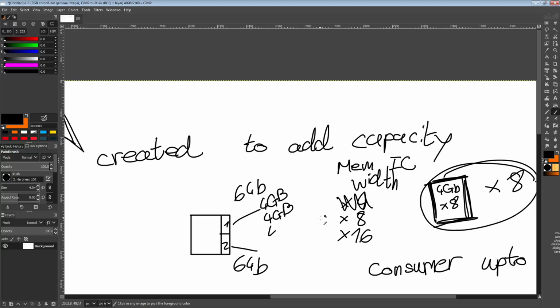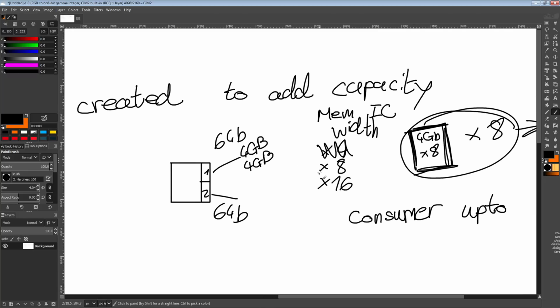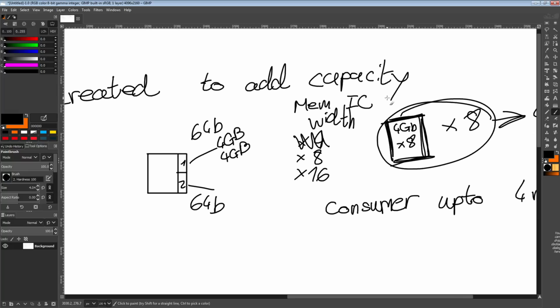Because then your motherboard needs to connect way more DIMM slots to the CPU, and you also take up space on the CPU die itself for the memory channels. So memory channels are very expensive. So memory ranks were created where it's just like, look, you can just plonk another group of memory chips onto the same memory channel, and that's called a rank.